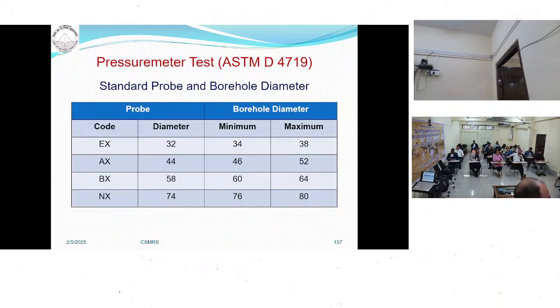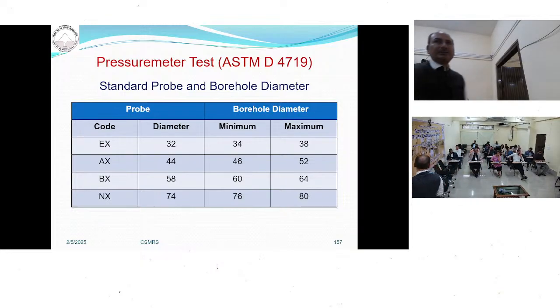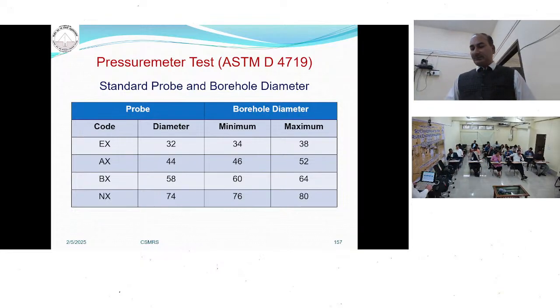Many times we have seen in projects that people say, "Sir, our borehole is ready. Please come and conduct the test." After reaching there, we found that the borehole diameter was more than 80 mm, and you are unable to conduct this test because the probe has a limitation to expand. Beyond that, we cannot expand it. So if you are conducting the test at 40 meters and you have taken 10 or 15 days to make that borehole, all your exercise will be gone. The only thing is that your borehole should be of accurate dimension.